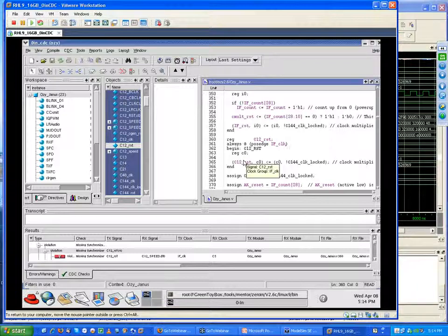It depends on the speed at which they're running them too. But I know, like in some of the Xilinx stuff, I was using some of the big Xilinx parts. I was running most of the stuff in there at 100 and something megahertz. I can't remember now, and then some at 200 and some at 400 megahertz. And I was in the upper 70 percentile of the usage. So yeah, good range is probably 40 to 70%. That's a nice range.